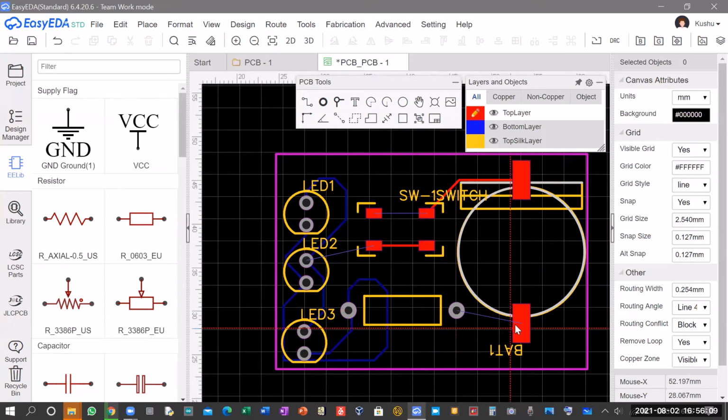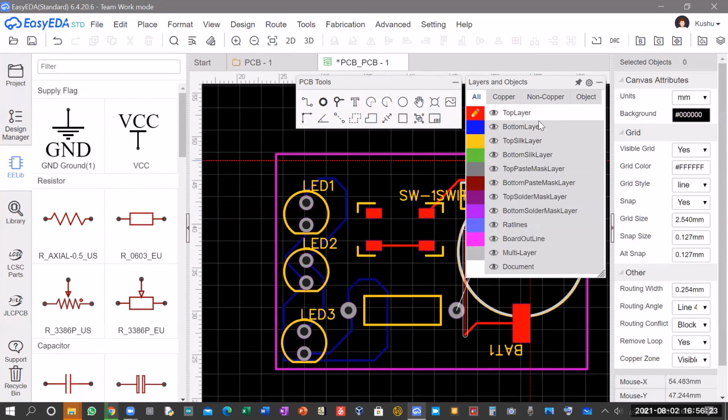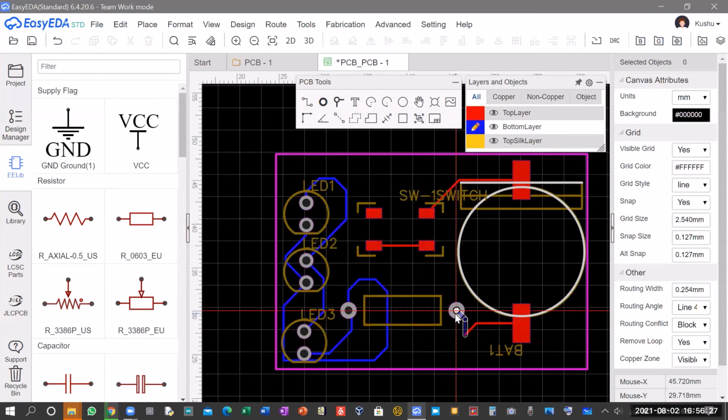Now is the challenge. I can take this wire to here, but the problem is this will be soldered at the bottom, not at the top. So you just leave it to a point where you think is good. Like I can leave it till the point here. Now let this wire come, doesn't matter. Go on the bottom layer from now and attach it here.